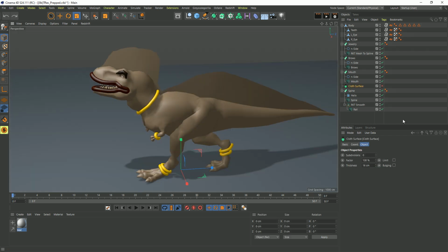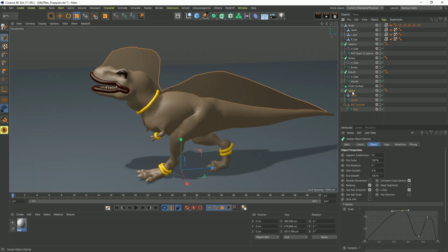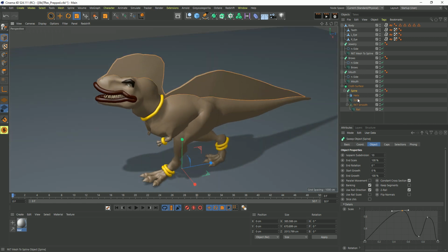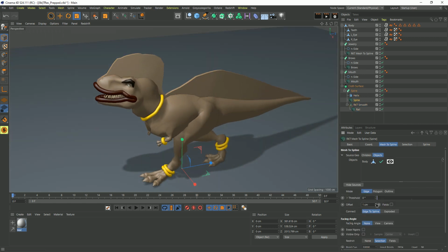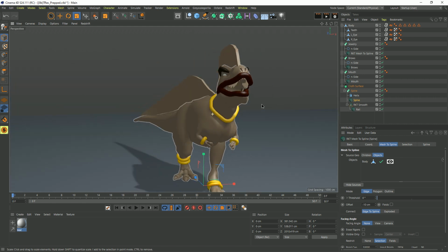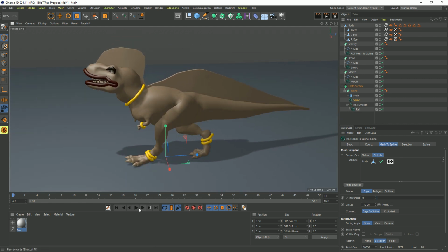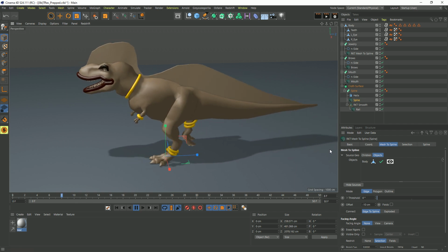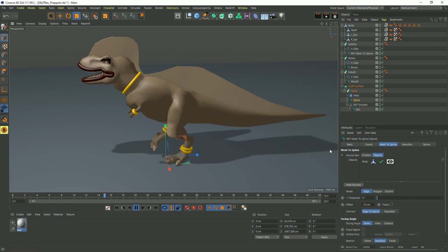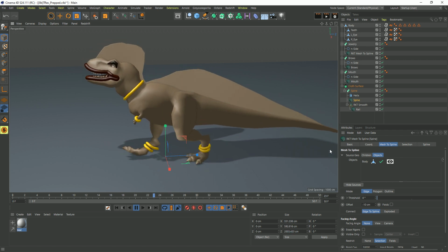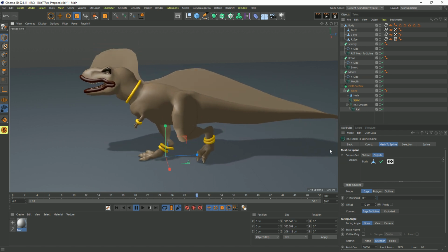Finally, let's feed all of that into this prepared cloth surface, turning that on. It can give that some thickness. Selecting our original spline, we could scoot this away from the body if we want to. We could also scoot it slightly inside the body if we want to make sure that that isn't sticking out at all. But our T-Rex is ready to go out and rumble. The best part being, if I hit play, everything is perfectly stuck onto this model. Any character you've animated, these will automatically stick exactly onto that mesh.